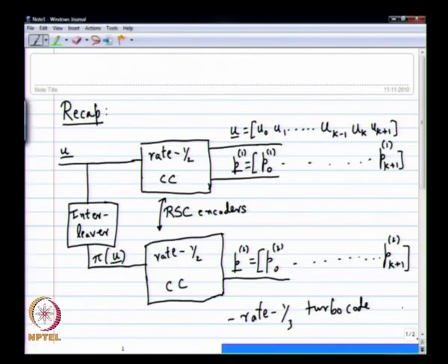Okay, now if you look at this picture, which is the most complicated part to implement in this picture? The interleaver, right? So everything else is trivial. It's just 3D flip flops. You don't even care about it. So the interleaver, you can't expect a memory of 1152 or something, a huge memory, and then randomly access it, pull it out. It's going to increase your power spent.